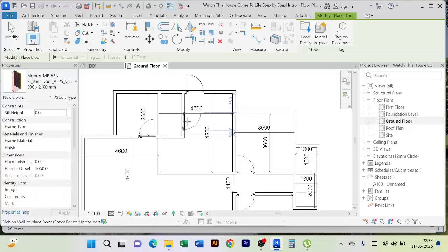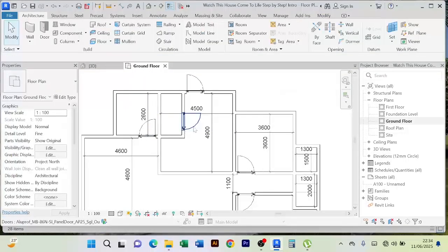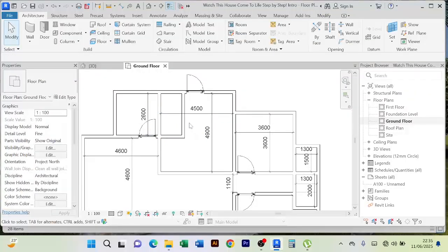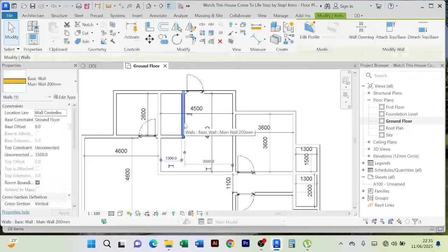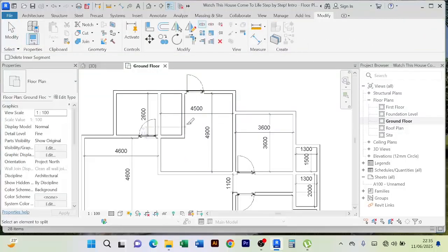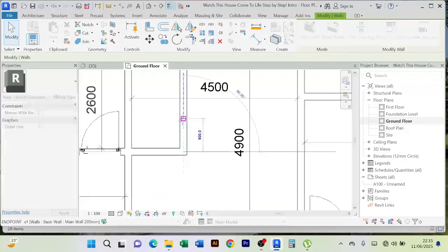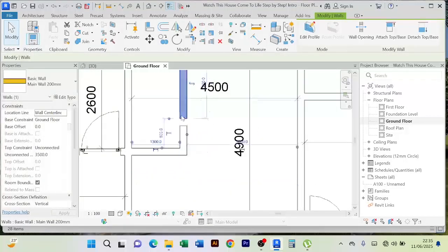Where can I have this? I think I can have it here. But really this pantry doesn't need a door, because this door is going to occupy all the space for nothing. What we are going to do, you click on this wall, you come to your split tool, the SL, you can split it here, then you just create a space. Or we are going to use an opening, just like that.